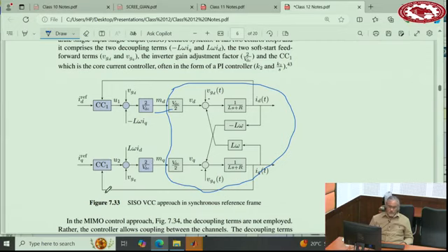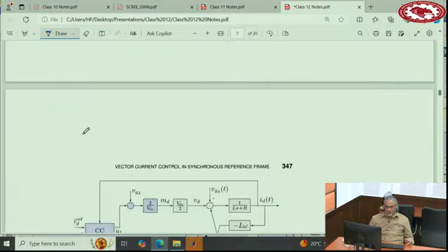And both these loops are like what? Like the single phase DC, right? That we started in the first part of the studies that we had. We already did that in detail, right? So full bridge VSC that we discussed, or half bridge, will be exactly the same as this one, half bridge VSC. So there is basically no challenge for designing this CC current controller. And I put CC1 and CC1 because both of them are the same. There is no reason for them to be different. And their design is very straightforward. We have already done it.